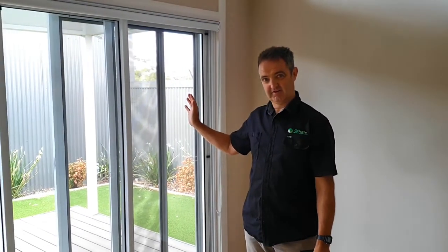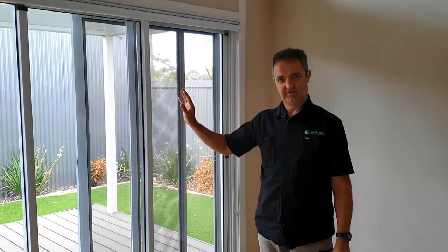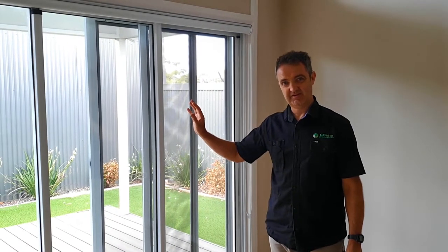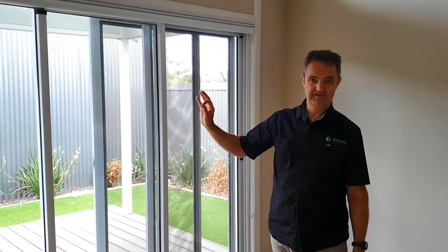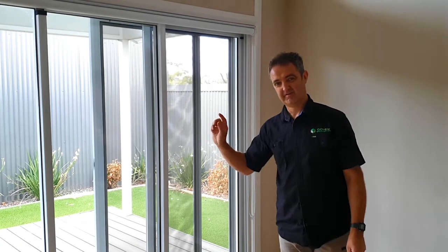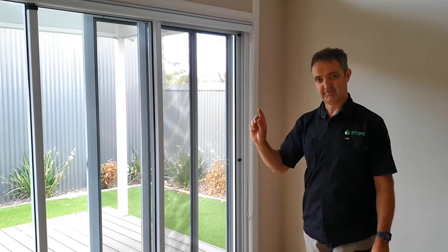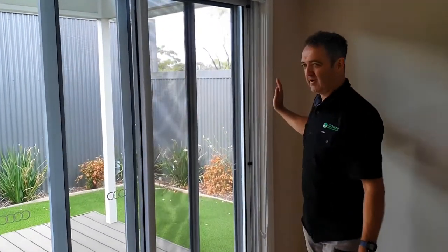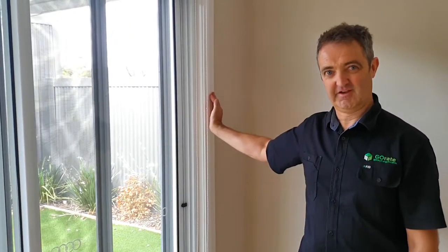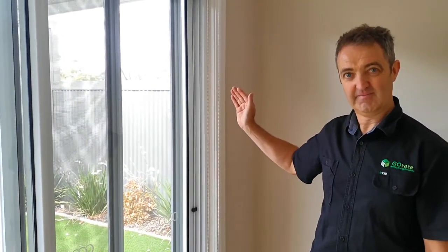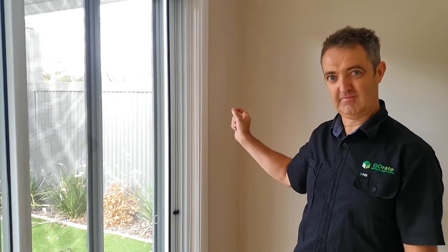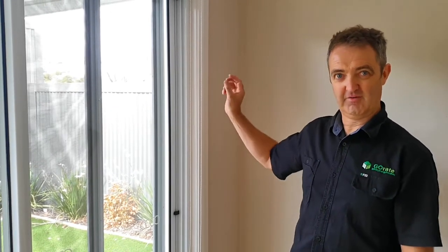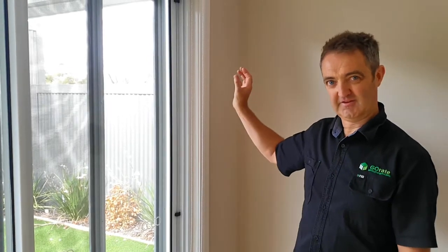Another point of air leakage is windows and sliding doors. Generally, glass sliding doors are a bit of a culprit for air leakage. Not the worst place of the house to have air leakage. But there's one little detail that most people don't think of. Now, quite often we talk about when we're building the house between the window frame, between the reveal and the wall frame, we put some low compression expanding foam or a mastic or something to seal that up.